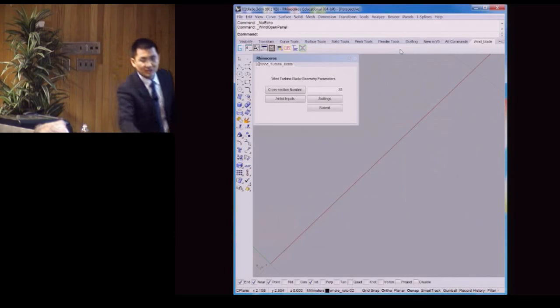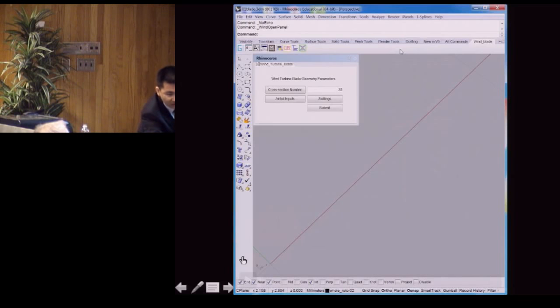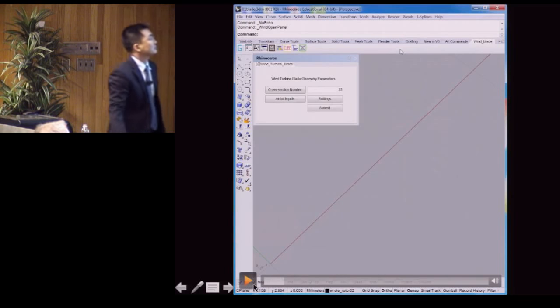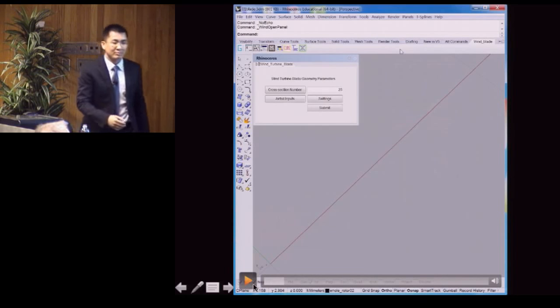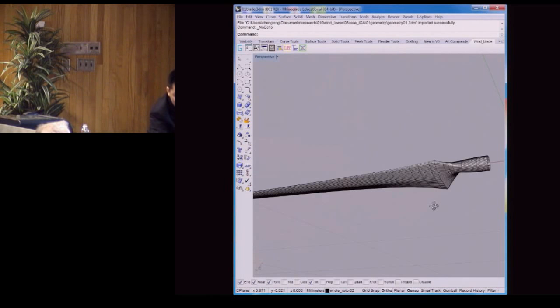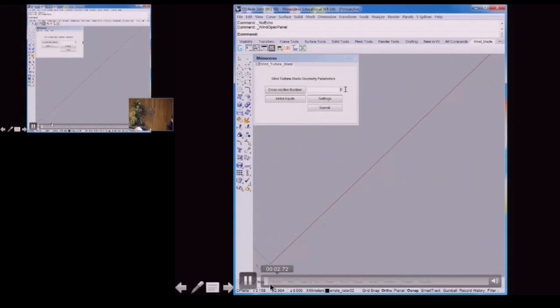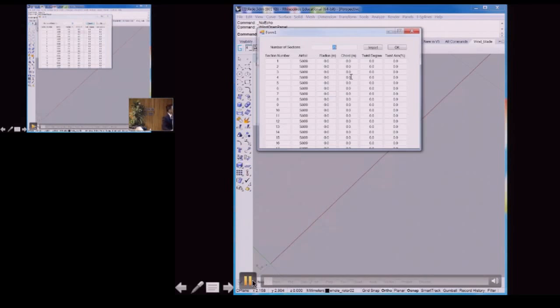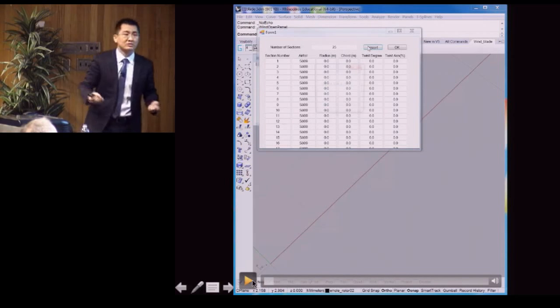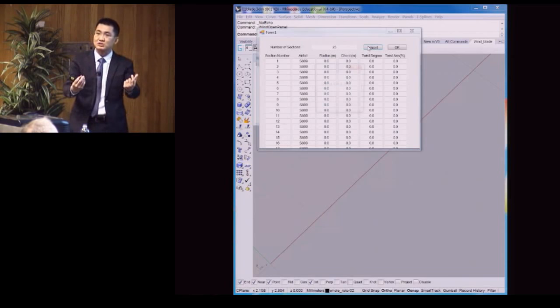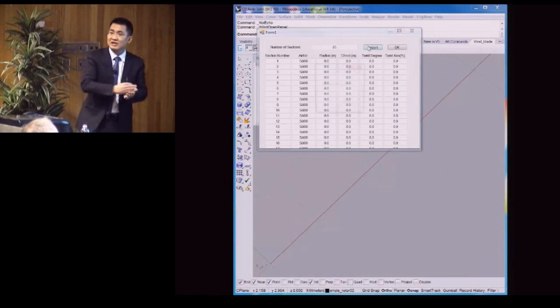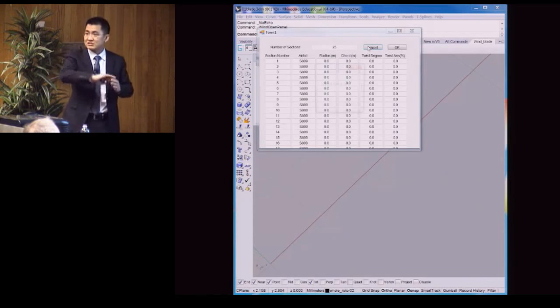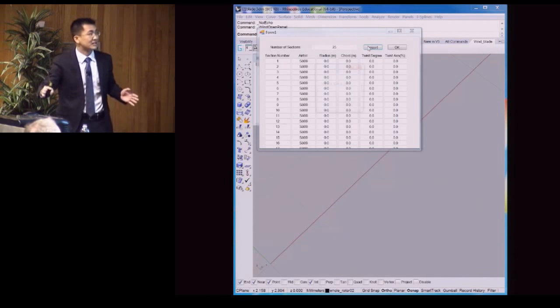What you see here is we would like to use this tool to design a wind turbine blade. We begin with something called parameter design. Sorry, let's go back a little bit. You can let the user input many parameters. How do you design a wind turbine blade? You come up with some 2D airfoil cross sections that could be locally optimized. You align these up, and then you have a surface based on all these 2D airfoil designs.